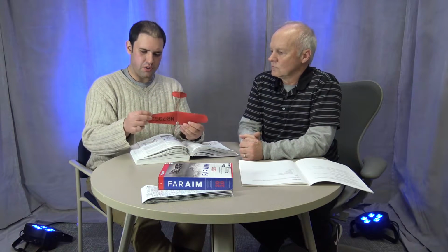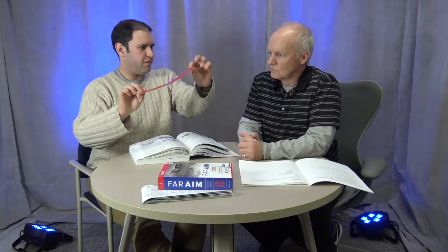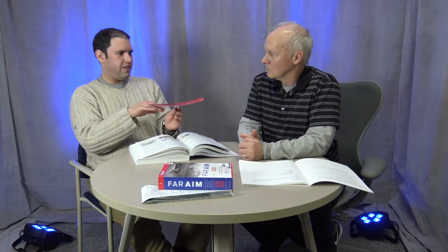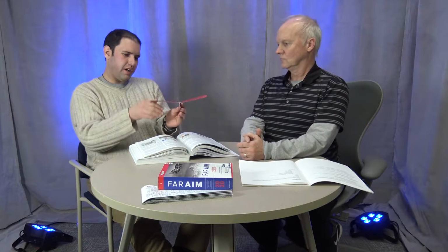So our control surfaces on the wings, on the trailing edge, we have ailerons, which move up and down opposite each other and roll the airplane left and right. The ailerons create more lift on one side and less lift on the other, to roll us left or right. The way that they do that, and this is something that you don't necessarily think about, is they're essentially changing the angle of attack of the wing.